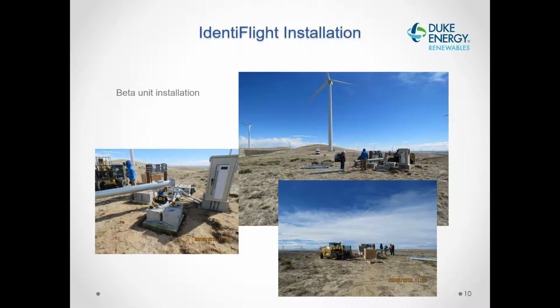There are several steps to getting it installed. It's very complex, and the more complex the technology is, the more important it is that you get it installed right. So we had several units that were installed with improper grounding, and a lightning strike nearby fried 4 of the units, which came back on us to fix. So it's important to get it right the first time.